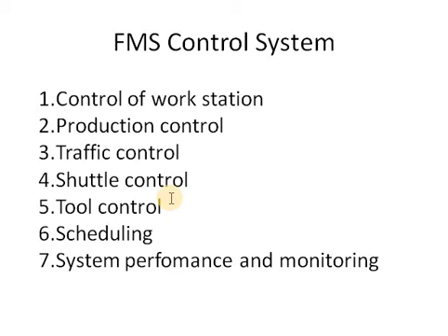Next, tool life monitoring. There are two aspects of tool control, as we see now: tool location accounting, and another is tool life monitoring. In tool life monitoring, the tool has to be continuously monitored while it is cutting. The tool is monitored for tool wear and tool breakage.